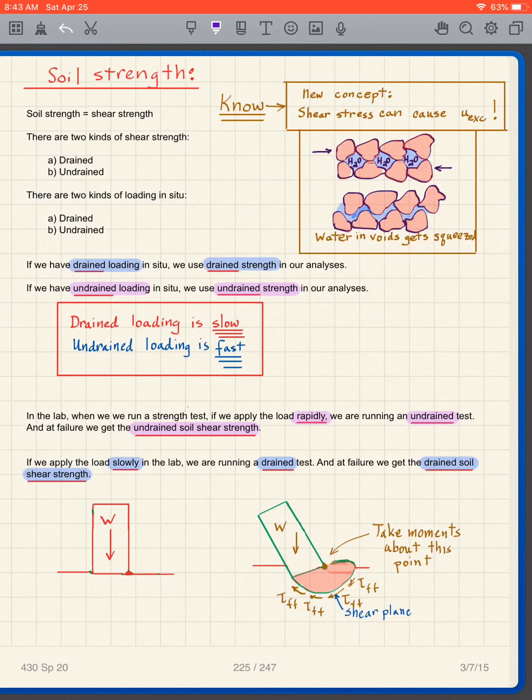the way we can see it is, if the soil particles, for instance, are sand or gravel, sort of as I've shown there, that excess pore pressure will be created, but it will dissipate very quickly because the water moves very quickly in sand or gravel.